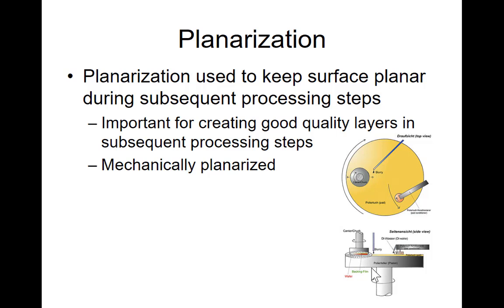Either way, you made the wafer, you process the different steps, you put something on it, and then the top surface is not flat, and you want to get rid of the top material, so you just do this CMP. You have this wafer, and then you have this disk that is just turning, and you may have multiple of these, spinning, turning, rubbing, and the wafer itself is also turning and rubbing, etc.